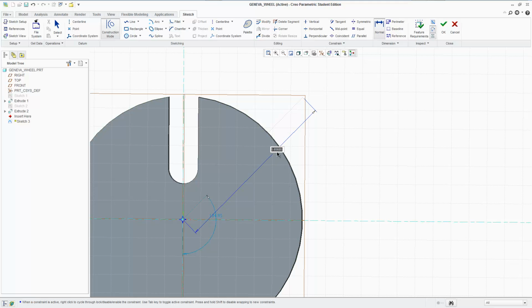If you double click, it says what I told it to be, and don't worry about that, it's just going to show you a random value. And to select the angle, you have that tool activated again. Click the line, then hold down control and click another reference line, middle mouse button click, and then you can change the angle. And for us it's 45, because if we're changing 90 degrees, this is the center point. The center point of a 90 degree iteration is going to be the 45 degree mark, right?